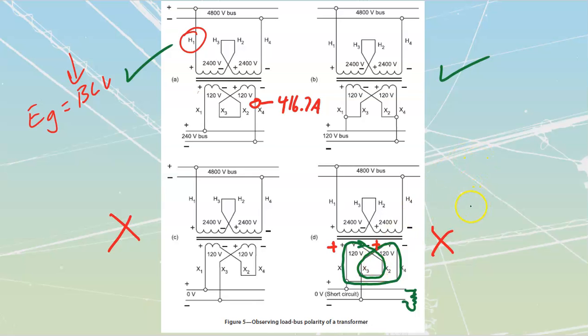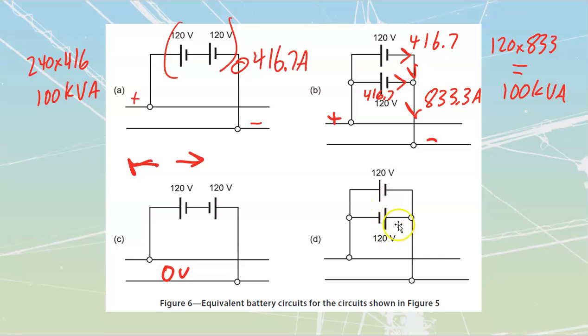And we know that if our secondary current rises, our primary current is going to rise as well. So on our high side over here, we are going to have an increase, a massive amount of current as well. It's not just going to short this winding, it shorts this winding as well, because the currents are lockstepped. They're going to stay together. This one gets to an uncontrollable amount. This one is also going to get to an uncontrollable amount that we're going to be pulling from this 4800 volt bus that we are going to have. It's a highly dangerous connection, this one.